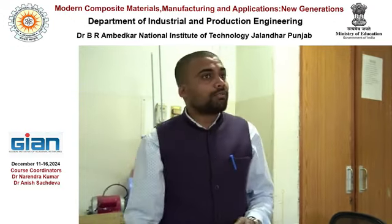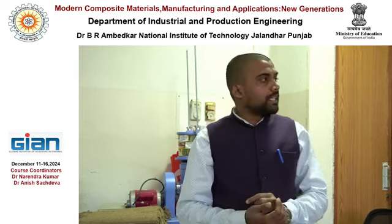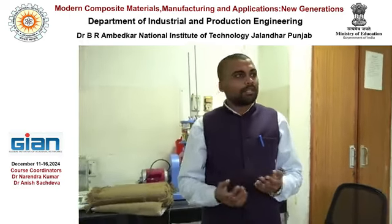So this is one of the common problems in the composite material, that is void, and how to avoid these particular voids. One of the ways is to use vacuum bagging technique, right?